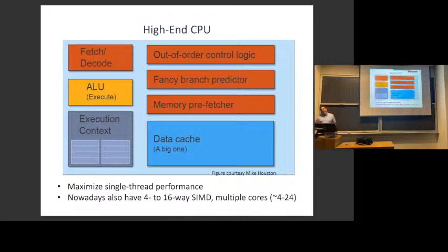But a modern high-end processor will typically have about 100 instructions in flight. It's launching multiple instructions every cycle. It's got a pipeline that's maybe 30 cycles long. So it's got about 100 instructions that are partially done, and some of them are further in the program than others. They're not even launched in order. But it keeps track of all sorts of bookkeeping so that you cannot tell. It never updates this execution context with an instruction until it knows that instruction is the next one that should have been executed. That actually takes a fair amount of hardware.